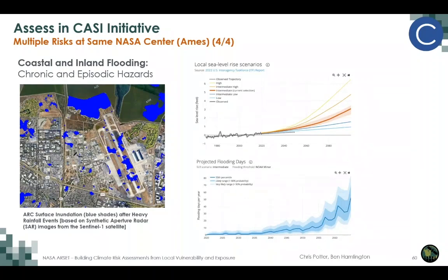And in particular, not only is the sea level going up, but you'll see a dramatic increase in the projected flooding days. In many cases, the episodic flooding events have a different pattern, and in many cases, a more nonlinear response than the average sea level rise itself. And of course, that comes from coastal flooding, including not only the mean sea level, but also the coastal surge, the waves, the run-up, and other conditions that can come along with a storm.